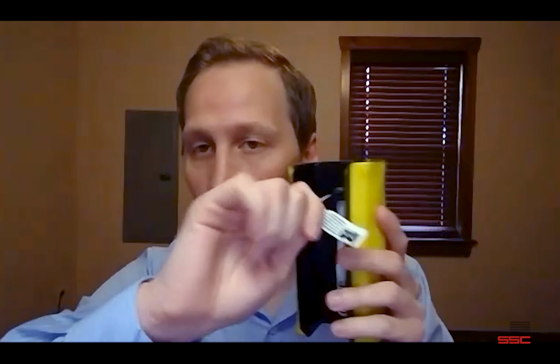One final option that I'll talk about, because it's different to doors. Those of you that are familiar with our door edges know we have a universal option for the MGR and the MGS options. For the round MGR and for the square, we have a universal option. It is different to what you see on doors. The universal option for these means that the wire actually comes out of the back of the sensing edge, the side that you're attaching onto the gate post itself, for example. What that means is you need to drill a hole through the post to pull this wire through and then dress it from there.